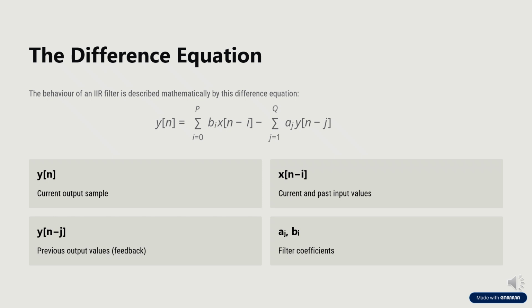So now if the value is greater than 1, the filter would be unstable because it will continuously keep increasing the output. For example, if I take an impulse input at time 0, the total output at time 0 will be 10 because there is no previous output. Now at time equal to 1, the input will be 0, right?